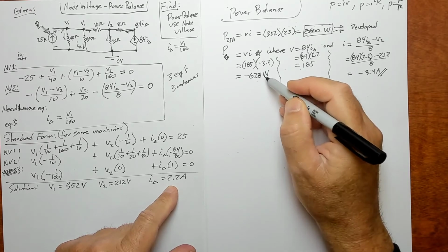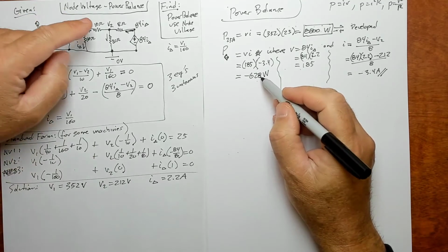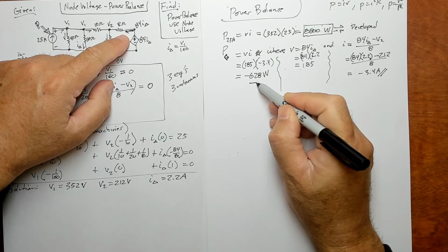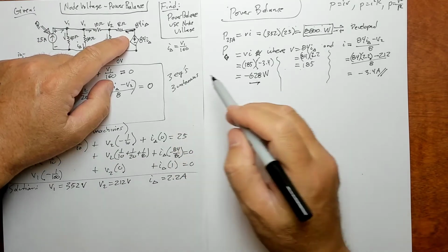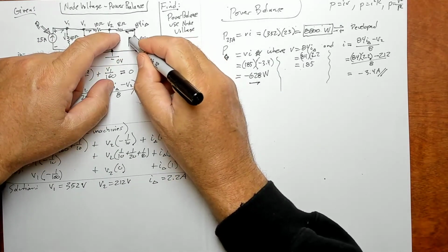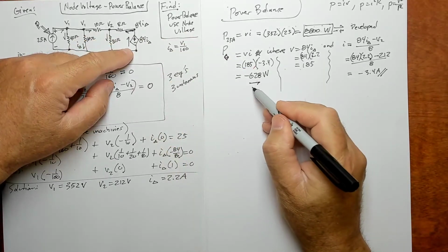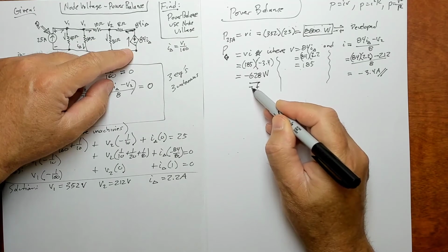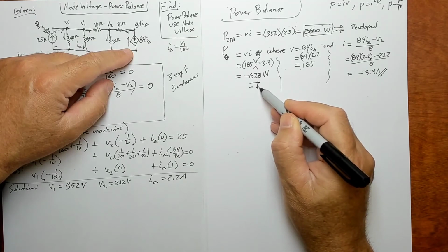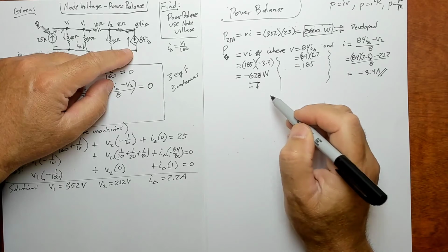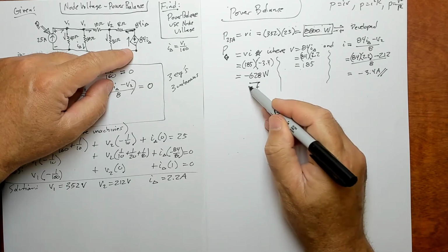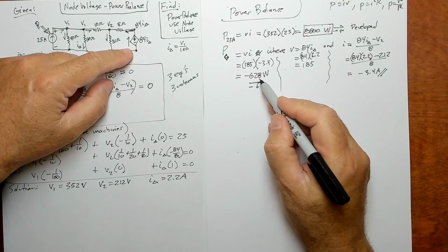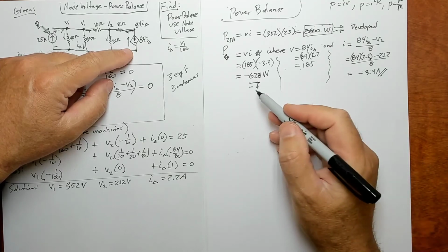And what about the arrows and junk? I've got an arrow direction, and you could redraw the arrow if you want, like right here, right? So it's coming in at a negative and coming out at a positive. So it's coming in at a low energy state and coming out at a higher energy state. So energy is being added to this by this sign convention. We have energy being added by the sign convention, but the value is negative, so we've got to flip that.